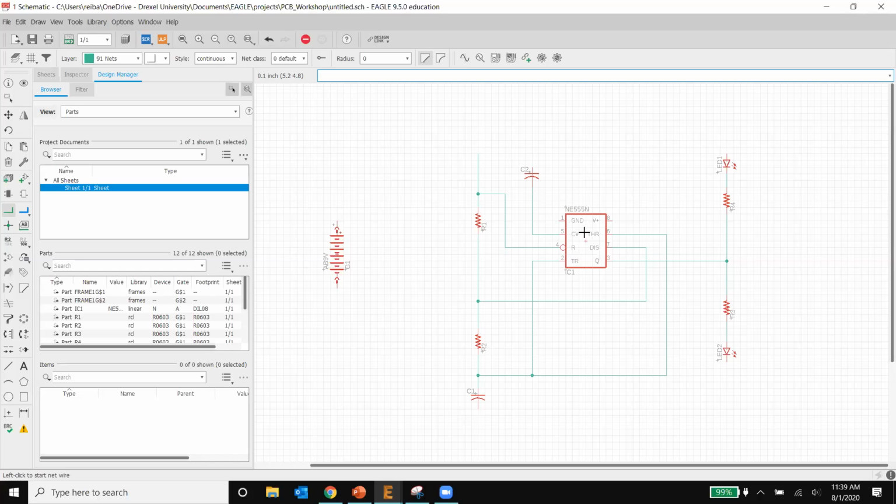Or I can take from the supply library a 9-volt supply and add it in here, and add it in here. And then, instead of wiring the ground myself to these pieces, I can just add the ground just like I did. It's the better way to do it.